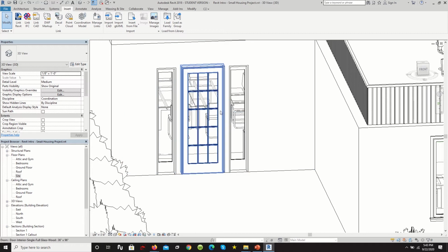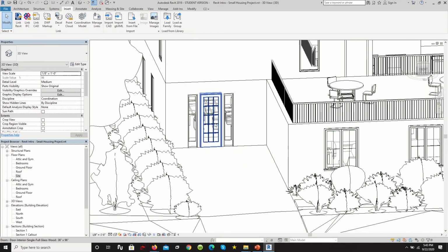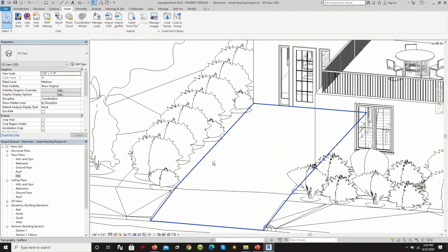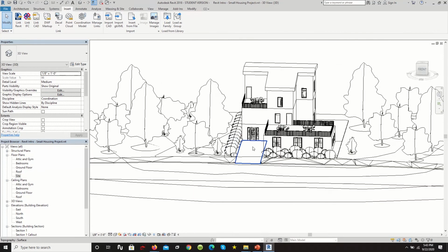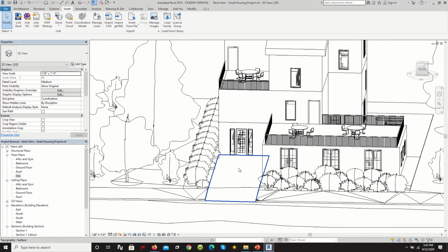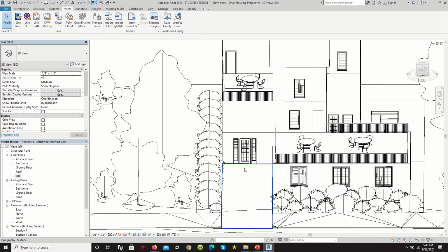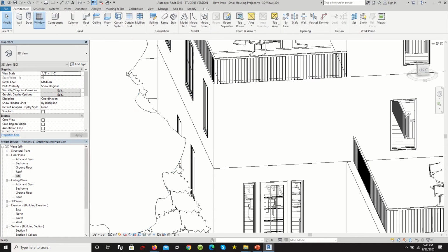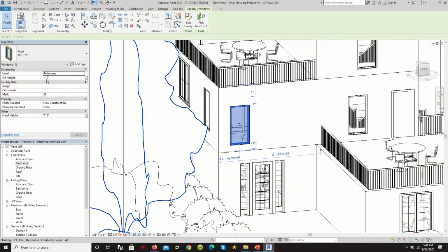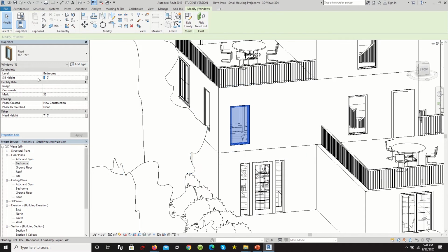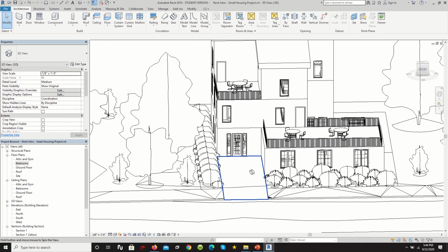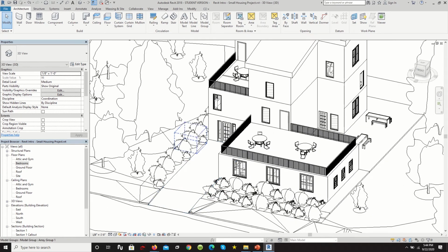So if you want, you can also just import a door handle for that, but we're not going to worry about that for what we're working on. We want to add the lamp post along the driveway. So we can go and do that as well. Actually, one more quick thing I want to add. I actually also want to add another window. Let's go on architecture, window, and let's actually adjust the sill height. Let's make the sill height perfect, so it lines up with what's adjacent. Begin to import our lamppost family.